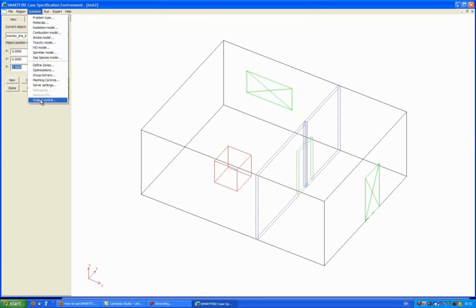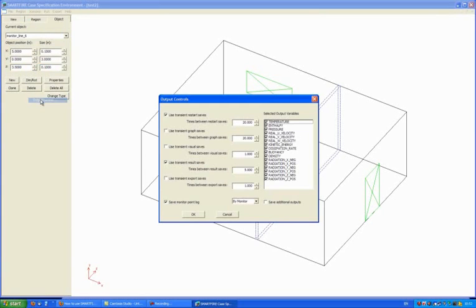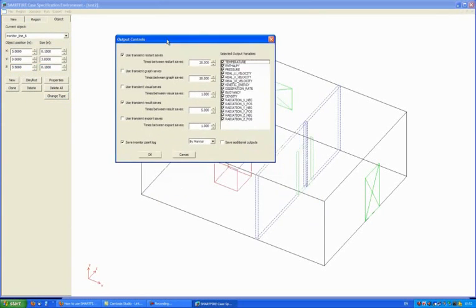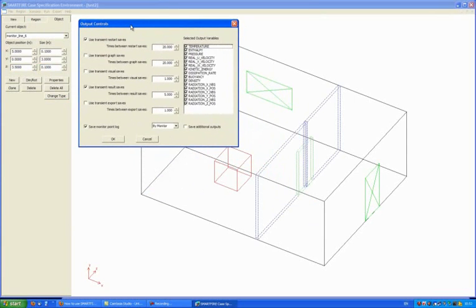There's very little point in running a CFD simulation if you don't obtain any useful results. So opening the output control menu, we see the options that are available. There are options for restarts. This allows you to go back to saved instances in case the simulation goes numerically unstable and does not perform well and may need configuration changes to be able to complete.